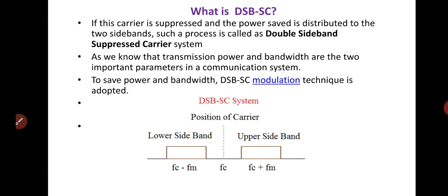As you know, the sideband frequencies contain all the information of the modulating signal. The carrier itself conveys no information. The carrier can be transmitted and received, but unless modulation occurs, no information will be transmitted. And when modulation occurs, sidebands are produced, and all the transmitted information is contained within the sidebands.